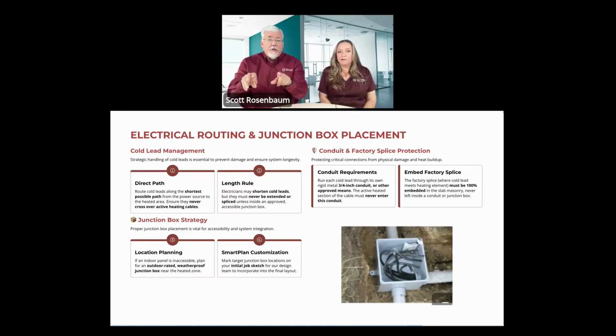And as we talked about, your electrician has got to be out there the day before, or two days before, because all of this labyrinth of wires, not wires because the wires aren't in there yet, but the box and all these tubes have to be there because that's what you're running the cables through. So that all has to be done in advance before anybody shows up to lay it out.